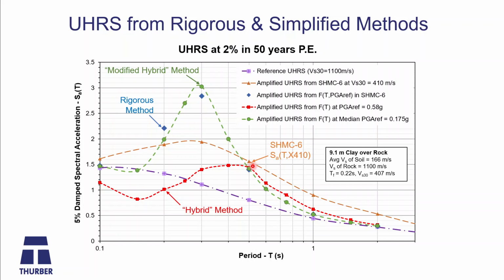So be careful if you happen to do structural design based on 0.5 seconds and you go, oh wow, it doesn't matter what method you use, they all give the same result. Well, it's only at 0.5 seconds in this particular case. And depending on the period of your site, that's going to shift, right?